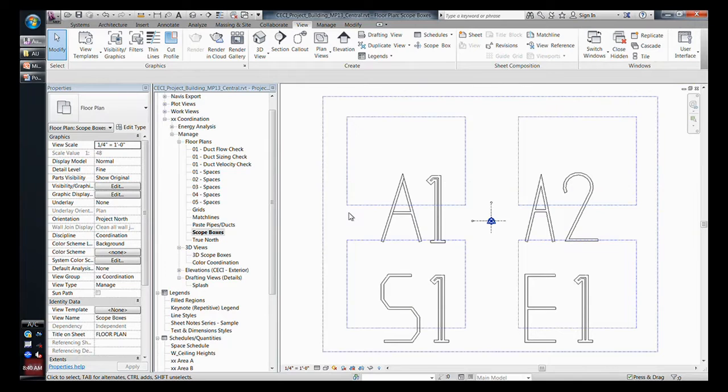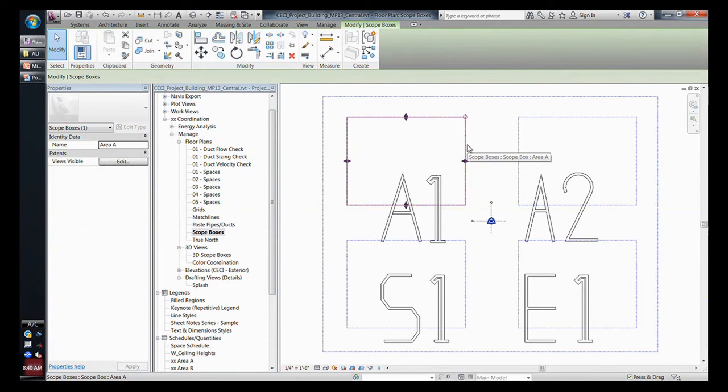great to be used for multi-story building that you need to create, obviously, level 1, level 2, level 3, level 4, HVAC, piping, hydronics, you name it, and you end up with, I don't know, 100 views that all need to be cropped to the same boundary of the floor plan. Scope box is what will allow you to do that. That's what I'm going to leave it at. I'm not going to have time to teach you how to use scope boxes, really. As you can see, what we're trying to do here is give you, as much as I can, various ways of utilizing the available tools.